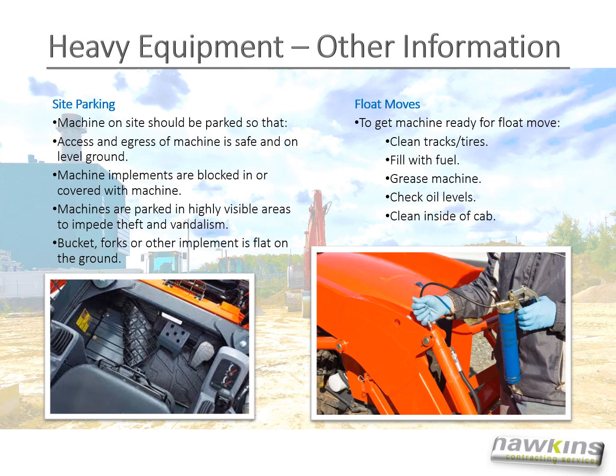Float moves. To get the machines ready for a float move, you need to clean the tracks or tires, fill the machine with fuel, grease the machine, check oil levels, and clean inside the cab.